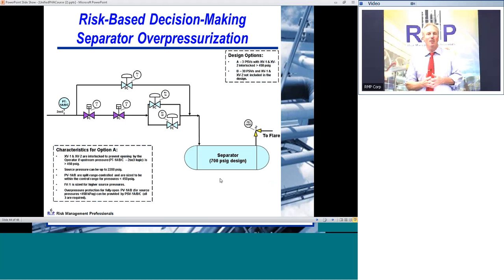There was no practical way to have relief valves that could do the job. A contemporary relief valve approach would have needed approximately 30 relief valves. So the design options were to have these 30 PSVs and not have isolation upstream, which was more contemporary, or to have fewer PSVs but active mitigation up front.